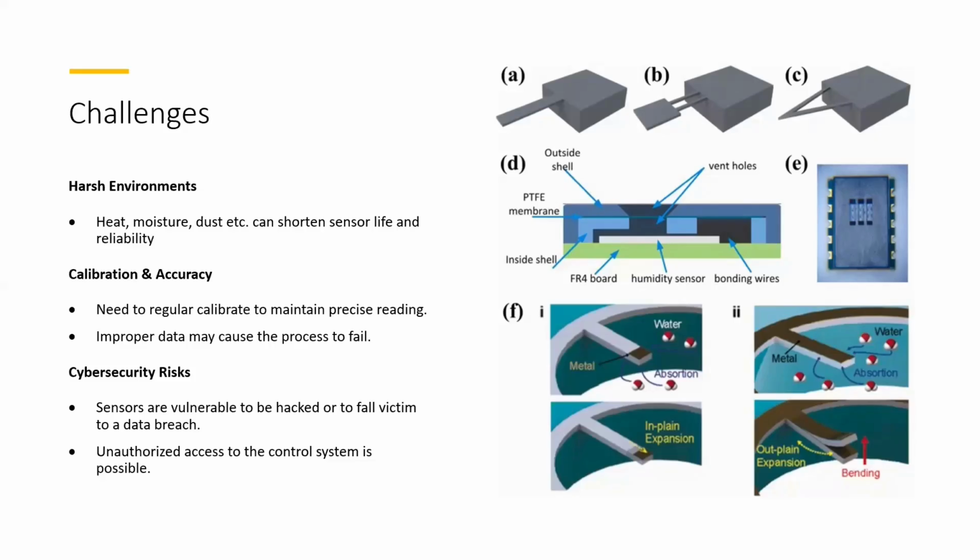This calibration varies per manufacturer. Most manufacturers offer instructions on how you have to carry it out. Some are quite complex and some are less complex. So these pose challenges, and you have to ensure you have precise readings during calibration of these sensors, because improper data can come as a result of poor calibration.